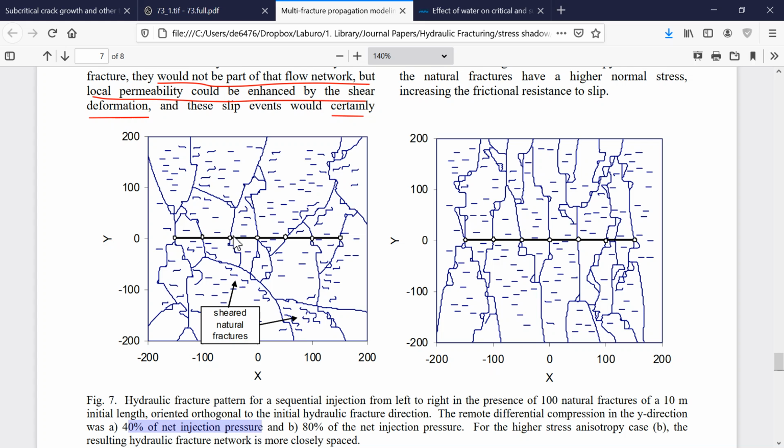For example, what we can see here is that there is fracture interference and interaction from different clusters, but also very important, and highlighted by this box over here, because of the presence of the fractures, we see that adjacent to those fractures, we can also have propagation of shear fractures because of the high stress intensity at the tip of some of these fractures that induce propagation of other fractures which are not the main hydraulic fracture, and eventually if they join, they might join into a larger fracture.